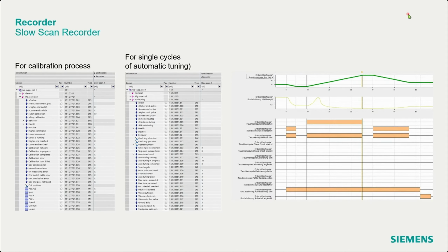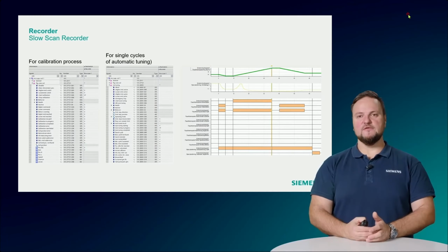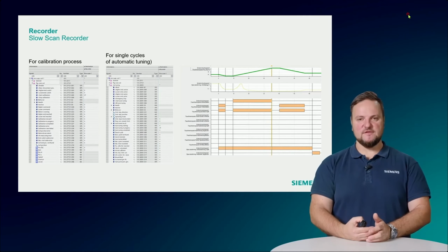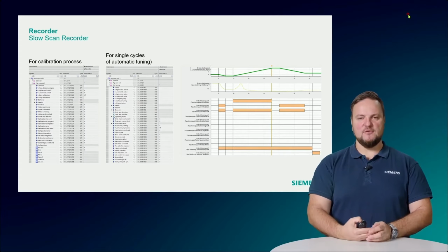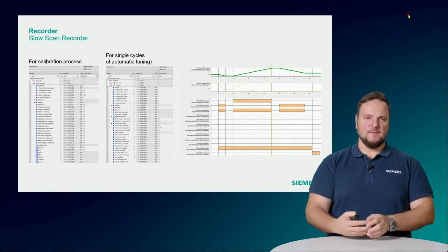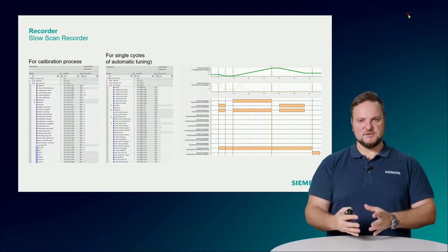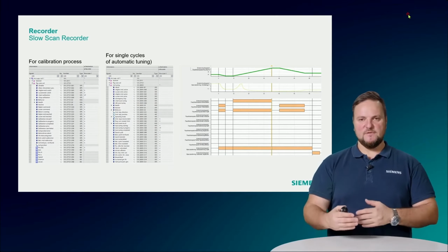And then afterwards, you have a fault record. You can analyze the fault record. You can also send the fault record to us, so that we can do the analysis. You see the real behavior of the displacement voltage, you see the coil position, you see all the binary information here of the arc suppression coil control. And this helps you to get a clear picture of the function. This helps you as well to find the right settings.